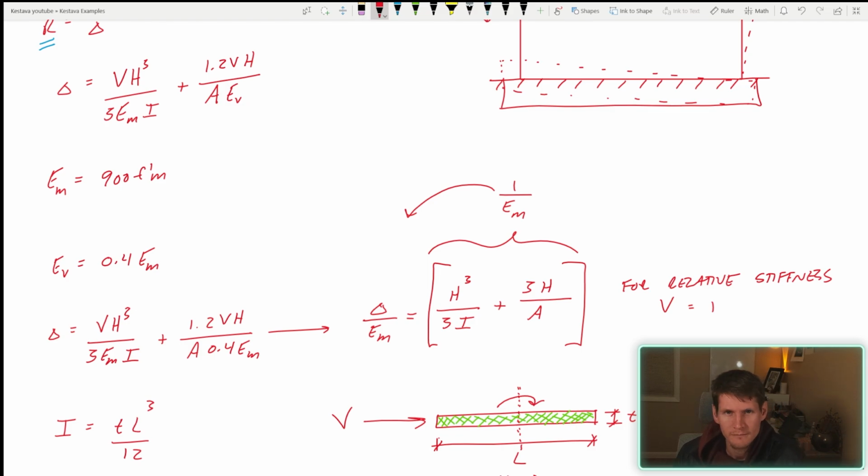If you have a change of material, this is going to change. This relationship is only for masonry. Otherwise, you have to get into Poisson's ratio and find G, because G is actually the thing that's supposed to be right there. So don't just jump to conclusions on this one. This is only specifically for masonry.